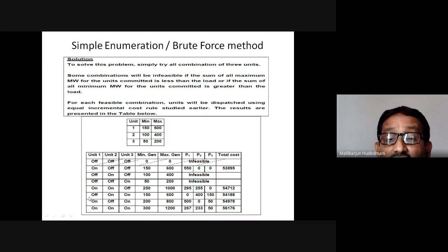So this is how the combination cost is worked out. Then this combination is effective. What is the range? 250 minimum megawatt production to the fullest capacity 1000. But my load is 550. For a 550 megawatt load, this combination definitely fulfills. The one was only generator 1. It was fulfilling. We don't know which I have to choose, so I have to check all the combinations initially.